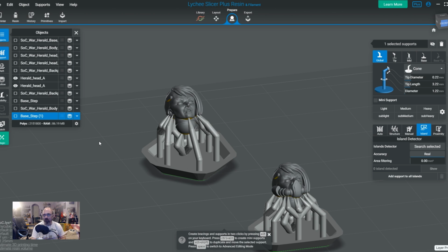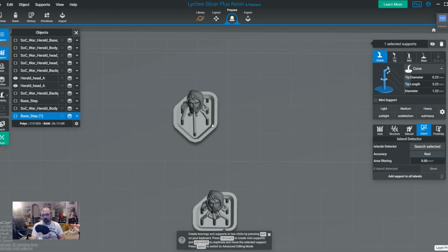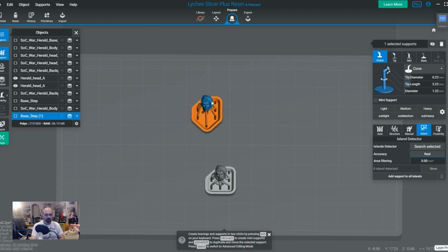Another issue I hear people deal with quite commonly as far as failures, that's something you can fix quite easily, is just essentially failing to check the print at different layer heights. Now, even if you're working with a pre-support file that you know is going to work, like it's from a reputable person, always check your print at different layer heights. This is a way to make sure that you get the islands at every single layer. And I'll show you what I mean.